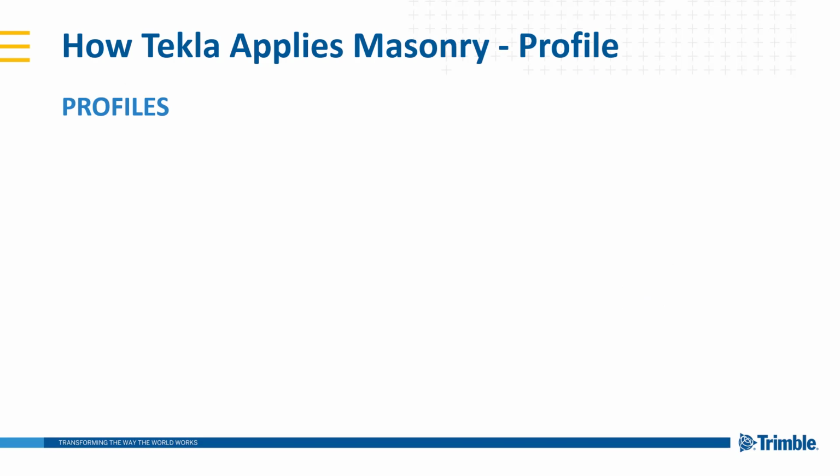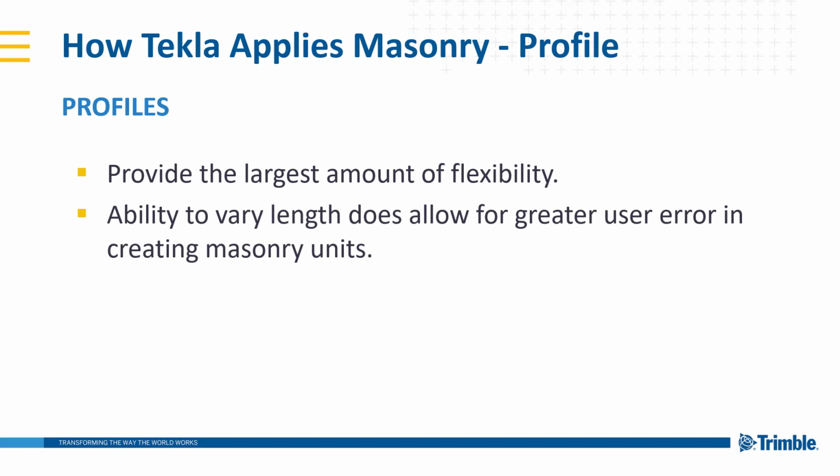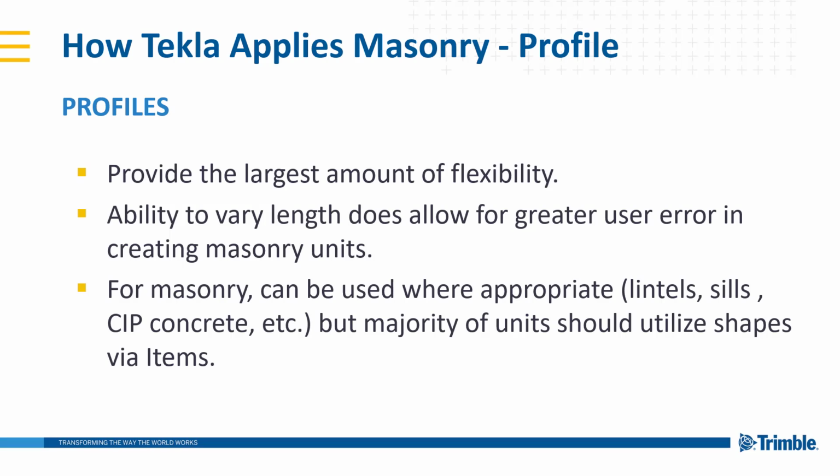Profiles do provide the largest amount of flexibility within Tekla Structures. However, it is important to note that their ability to vary in length does allow for greater user error in creating masonry units specifically. Now, that isn't to say they shouldn't be used for masonry. They should be used where it's appropriate, for lintels and sills, or even some cast-in-place elements that associate with your masonry units. But the majority of units should be utilizing shapes via items.